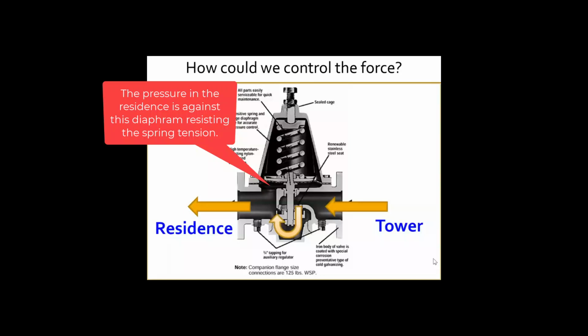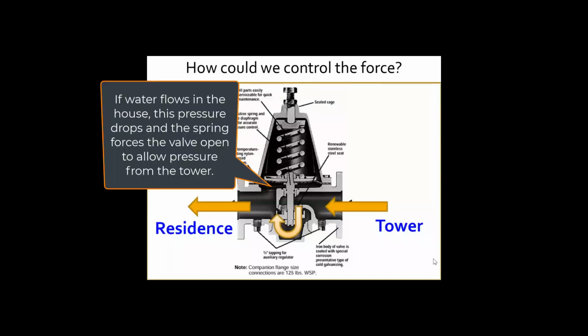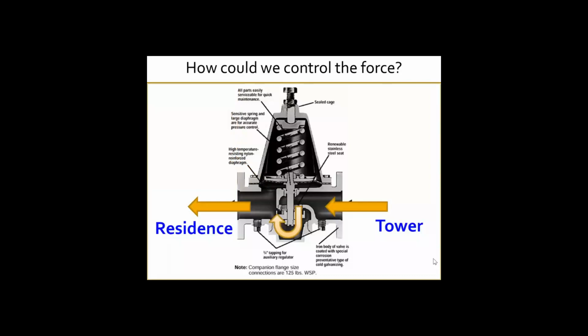One of them is the spring, which you can see in kind of a cutaway view there, and maybe you didn't recognize that right away if you're not used to looking at this kind of diagram. But in the upper portion of this regulator, you see the cutaway view of a coil spring. At the top of that coil spring, you see a threaded bolt with a lock nut, so you can screw that bolt in, and that compresses the spring. Now, what you may not see quite as easily is that the spring is pushing down because it's pushing against the outside of the casing.